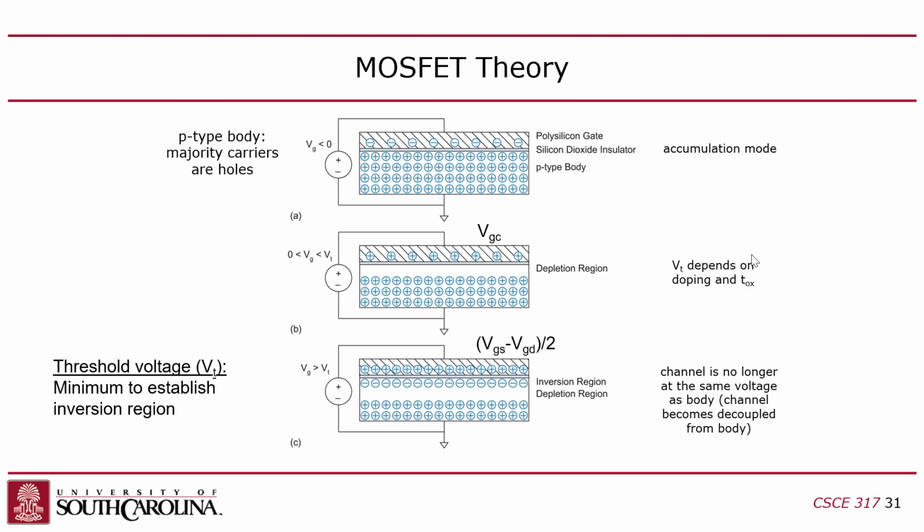In this case, this is an NMOS transistor. I start putting a positive charge on the gate, and those holes in the substrate start moving down and away, kind of like a reverse bias diode. You start to repel the majority charge carriers. That's what happens when you try to send current the wrong way through a diode: the charge carriers move away from the junction. In this case, it's not a junction, it's an actual capacitor separated by glass. But then eventually, you'll attract the minority charge carriers, and they'll form the channel.